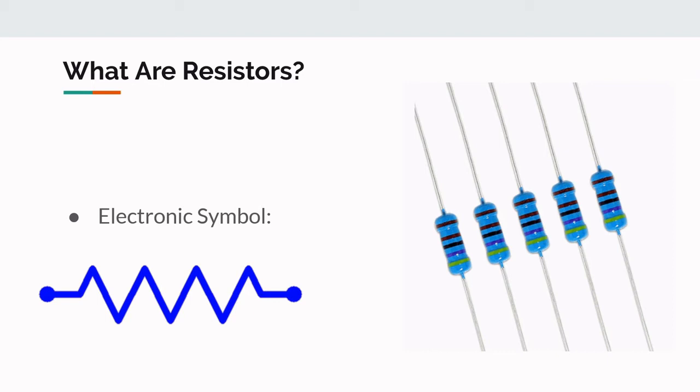If you break open a resistor and scratch off the outer coating of the insulating paint, you might see an insulating ceramic rod running through the middle with a copper wire wrapped around the outside. A resistor like this is described as wire wound. The number of copper turns controls the resistance very precisely. The more copper turns, the thinner the copper, the higher the resistance.